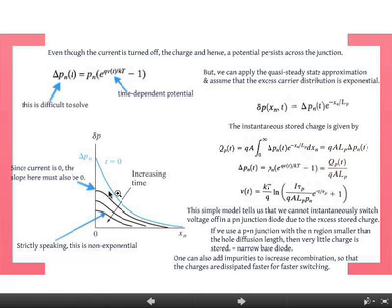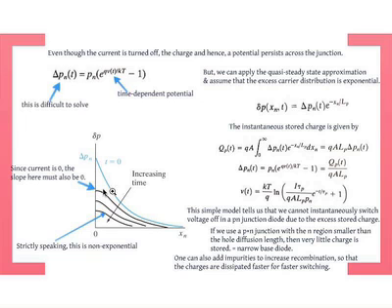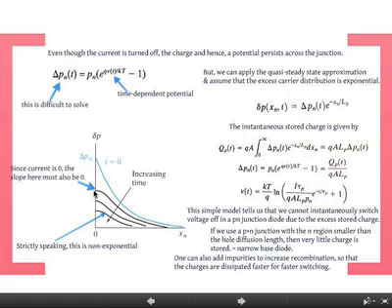Now, coming back to what I said before, that this approximation is not strictly true. This has to do with the boundary conditions. So if you look carefully at this boundary, this gradient here, so first of all, remember the diffusion current is proportional to that. Okay? So at the junction, my diffusion current has to be 0, because I've turned it off. Which means at the junction, the slope here must go to 0.